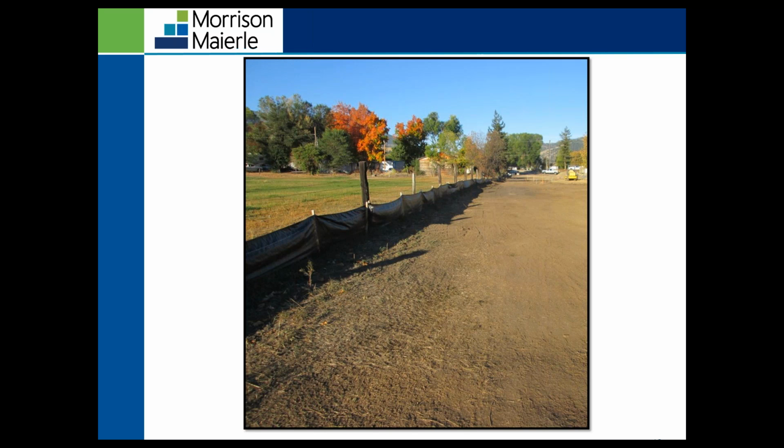So this is a BMP that you see on a lot of sites, but I always call it a maintenance nightmare. You know, there are the wooden stakes that are going to be breaking. That fabric there is only really designed for 5 to 8 months. Then it's going to rip and tear. So it's just going to require a lot of maintenance for it to be effective.